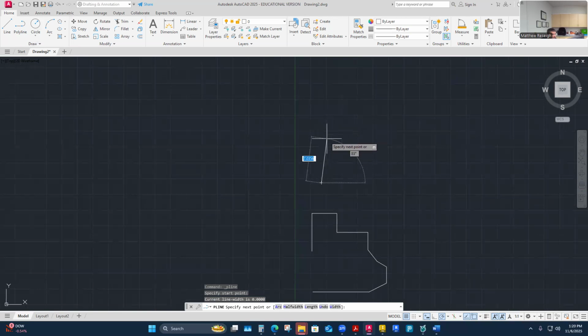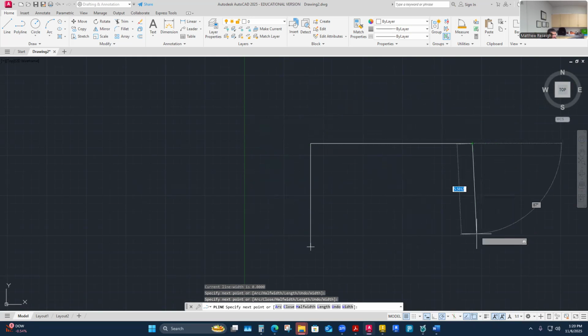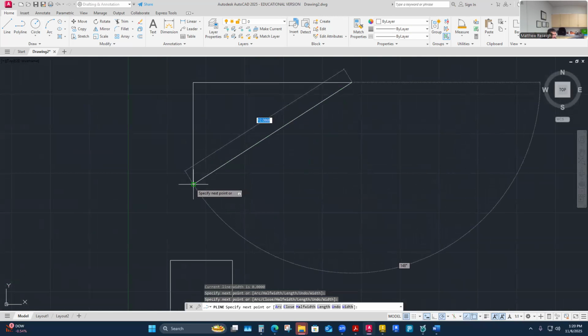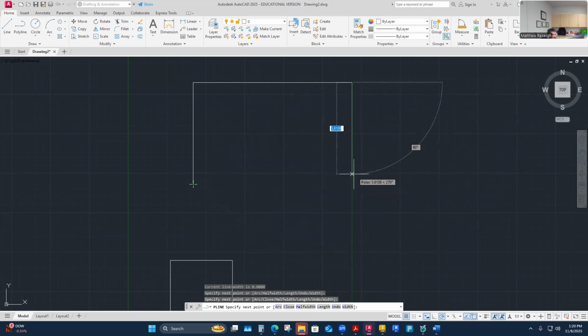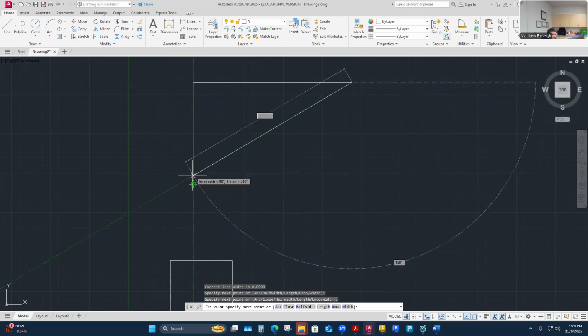If I just draw with it for a second, let me show you. I won't make any arcs or anything. I'll just do a line to a line to a line. Oh, and here's one thing. If I wanted to connect this to itself, I could cursor over here and target that point. I'm not clicking, but if I pull away, object tracking allows me to reference a point. I'm not clicking on the point, I'm just referencing it.